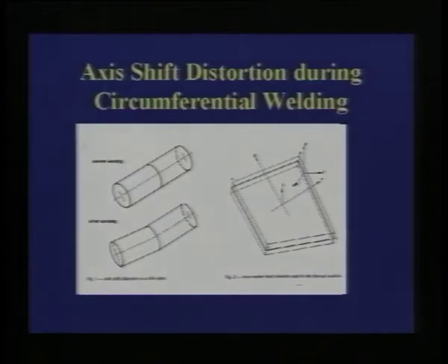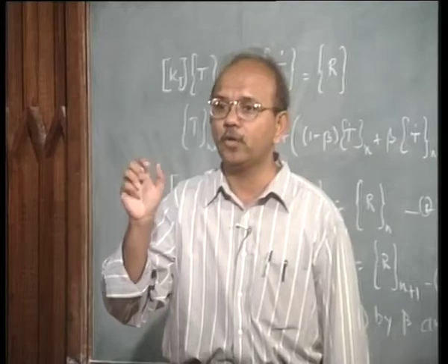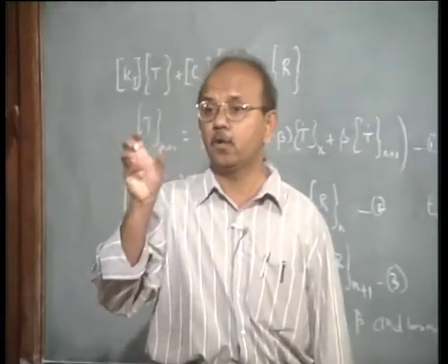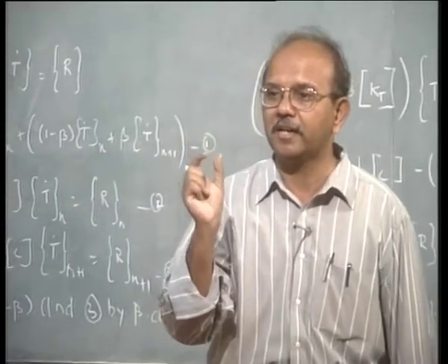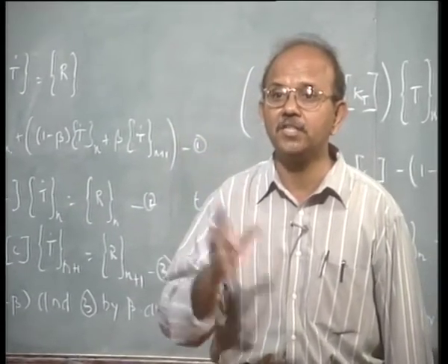Please note that because of temperature changes and temperature gradients, there are thermal expansions. Remember that when we derived one of our first lessons on stiffness matrices, we saw that there is a strain term. How do we handle the initial strain term epsilon 0? Go back and see those notes. You will see that we had already indicated that it is possible to handle initial strains.